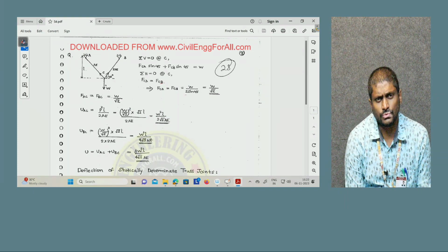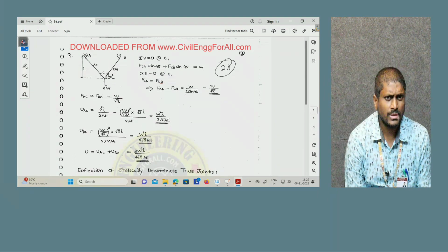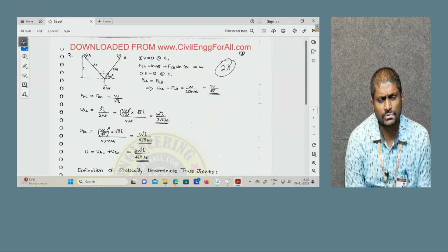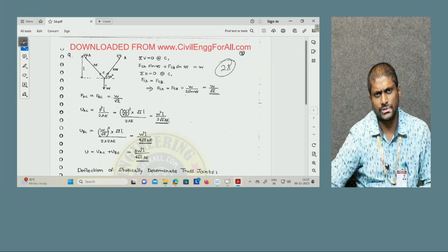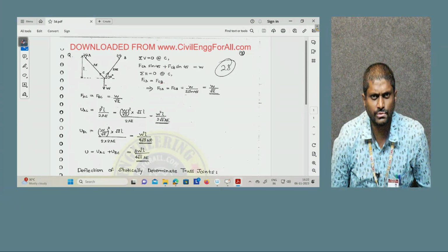Here the axial rigidity is given as 2AE, 2 times AE, for the BC rope, whereas for AB and AC it is given only as AE. Then you can apply the regular procedure: summation of vertical forces equals 0 at C. Then FCA sin 45 degrees plus FCB sin 45 degrees equals W, whereas summation of H equals 0 at C, that means all horizontal forces equal 0 at C.